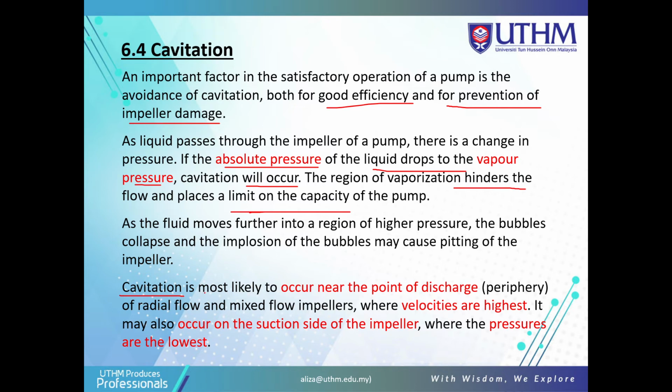Cavitation is most likely to occur near the point of discharge of radial flow and mixed flow impellers, where velocities are highest. It may also occur on the suction side of the impeller where the pressures are the lowest. So maybe your question asks you to briefly explain cavitation in a pump. So you can explain this concept of cavitation.